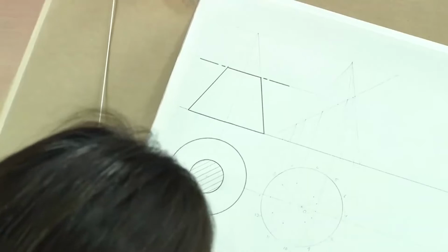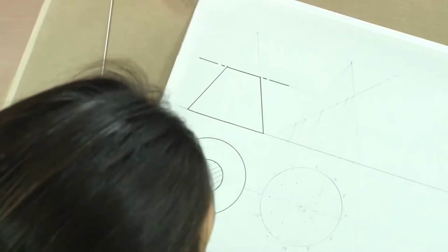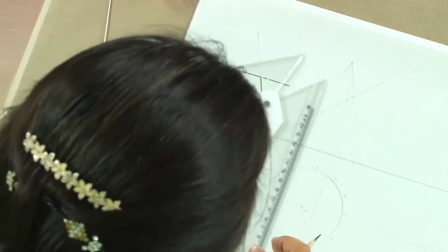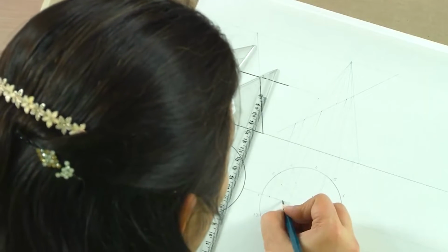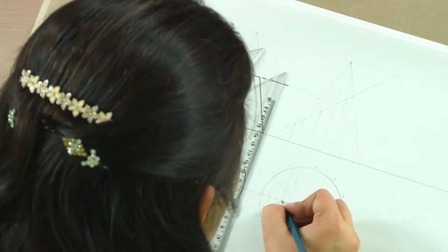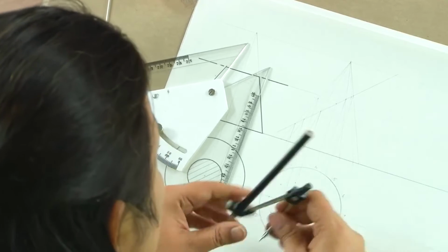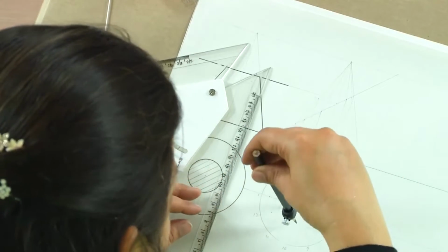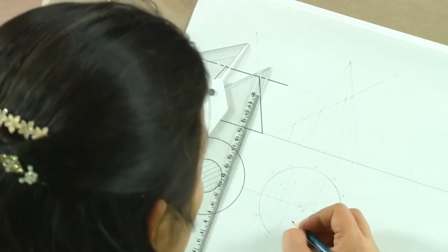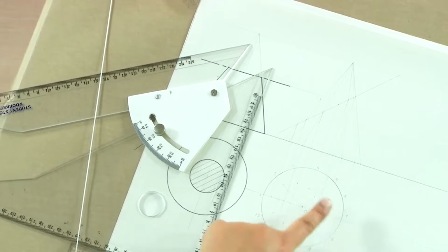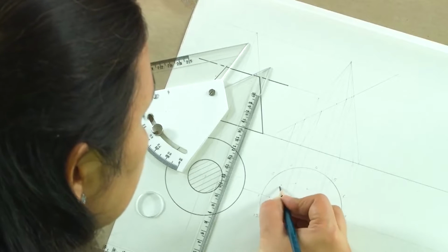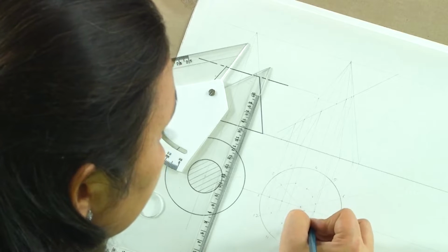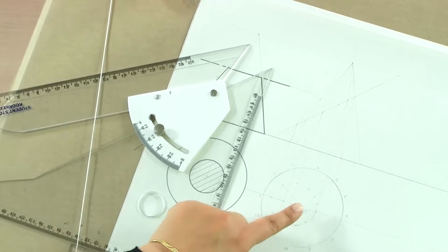Now for this one, if you remember the same concept, if we were to have a section plane parallel, what we will get? A circle, same distance at these two generators. So we will take the same distance at this generator here, which is this point, and now the same distance as this point has from the apex will be the distance that we will have on these two generators. So these are the remaining 2 points. If we see it from the top, this will be appearing as a distorted ellipse. So that's the shape that we are getting here, and the apex is chopped off.